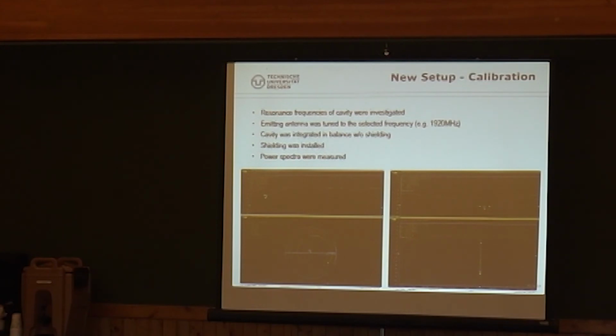When I closed the cavity again, I already saw a quite well matched cavity. After this pre-tuning, I was able to use my three stub tuner and reach nice peaks like this one with, let's say, S11 values of -50 dB, for example. I don't want to say that number too loud. And also very high Q factors.